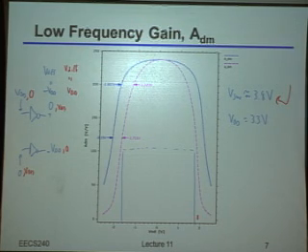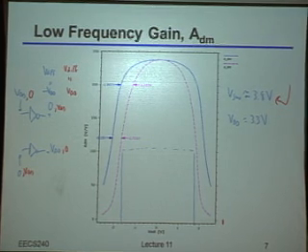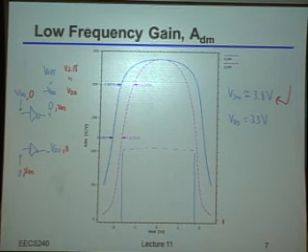So if you look carefully at these curves, you'll see that everything is totally symmetric. If I go on the negative output voltage versus the positive output voltage, everything looks the same. Now, that's to be expected, because we are talking about a differential circuit here. If I have a negative output voltage, then on the other side of the circuit it's positive, and if I flip it, the exact opposite thing happens. So there really should be no asymmetry in this curve.